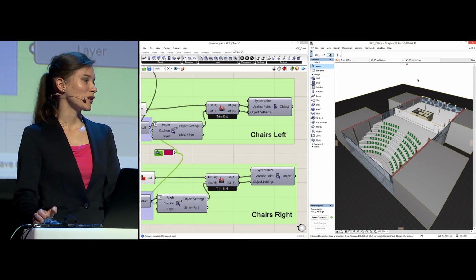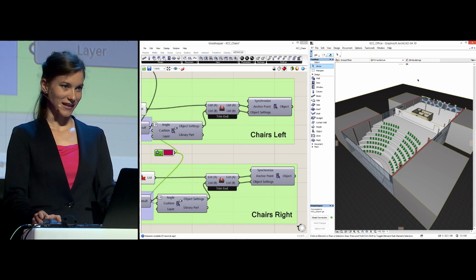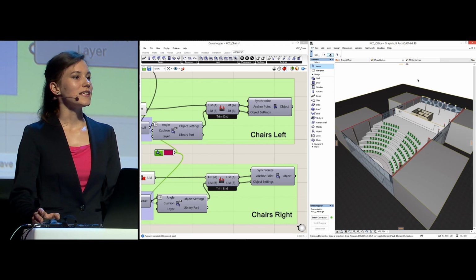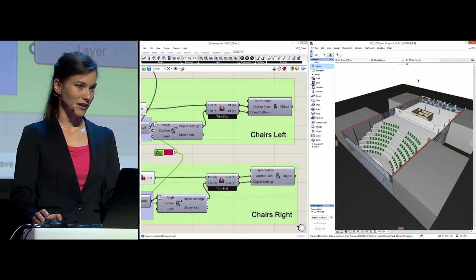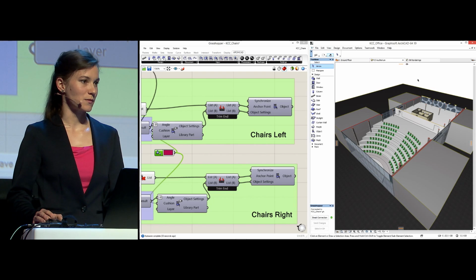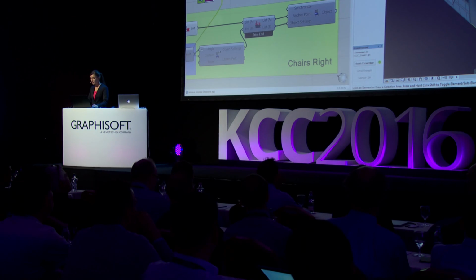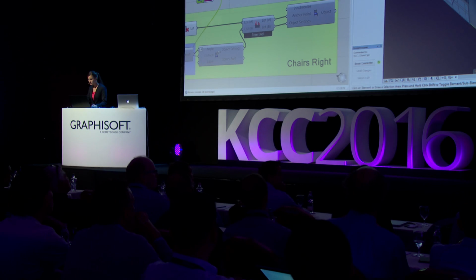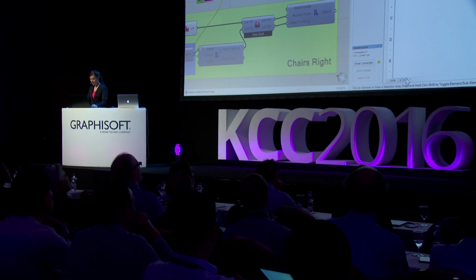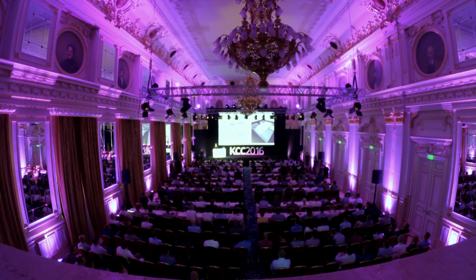Since we're architects, we need to keep an eye on data from the earliest phase of design. In this case, we need to know exactly how many people can fit into this room. Since we are building here a full-fledged BIM model, this information is available automatically. We only need to open the schedule and check the number. It's 118 now. It won't be enough. The clients want more. Well, what can we do?